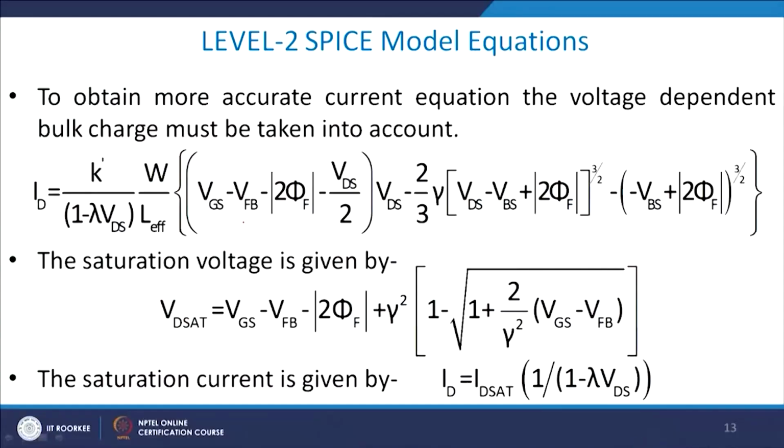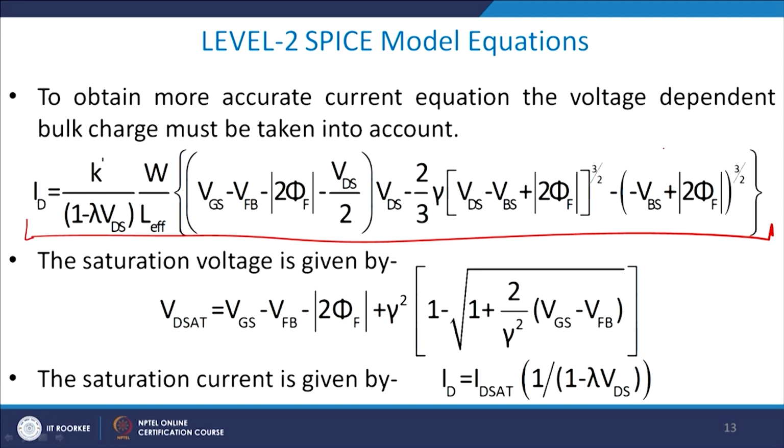Let me come to the SPICE level 2 model, where in this case the voltage dependent bulk charge must also be taken into account, because please understand the bulk charge varies with the applied voltages, and depending on that people have found a new equation, given by this big equation which is used in SPICE. Do not worry, but more importantly you can see here that VBS comes into the picture, which means the substrate effect is being taken care of in the SPICE level 2 model, and you do have gate to source voltage, flat band voltage and so on.